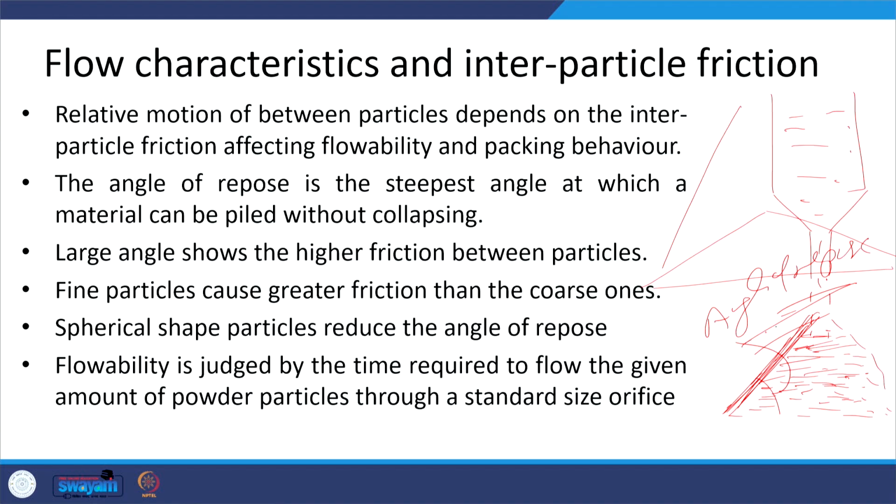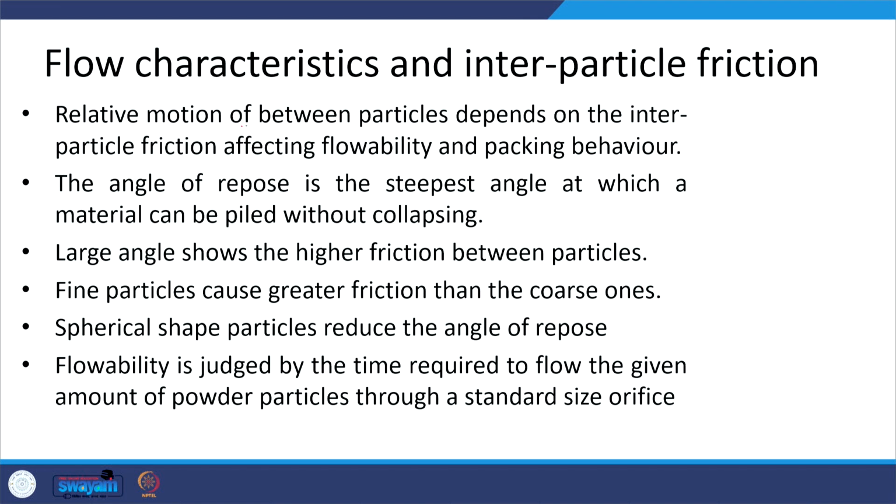If the interparticle friction is more, obviously flowability will be less. The voids and the gaps between the powder particles will be more, and that in turn will affect the packing behavior. Okay, so relative motion between the powder particles depends on the interparticle friction, which in turn affects the flowability and packing behavior.